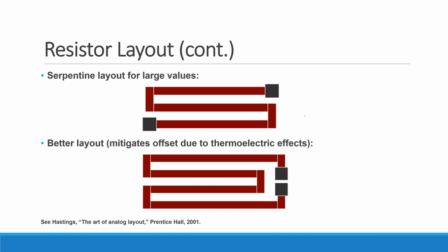Turns out there's actually, particularly with resistors, life can be even more fun than this, because a lot of the materials that you like to use to build your resistors out of turn out to be somewhat thermoelectric, meaning that if the temperature is different, then it actually generates a slight change in the voltage. And so, if you want to avoid that, there's these sort of extra tricks you have to play.